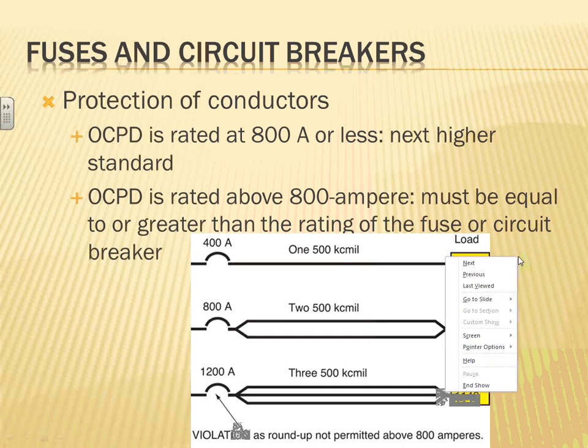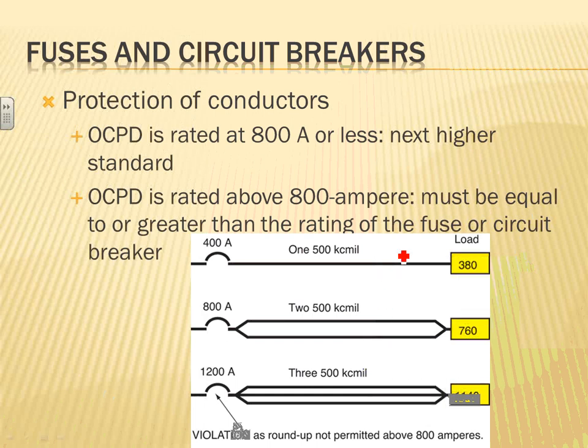That's a very good point. Unless, you know, wait a second. A circuit breaker doesn't trip at 80% of its rating. That means that a circuit breaker could only handle 80% of its rating on a continuous basis. So this, it's still not going to trip.